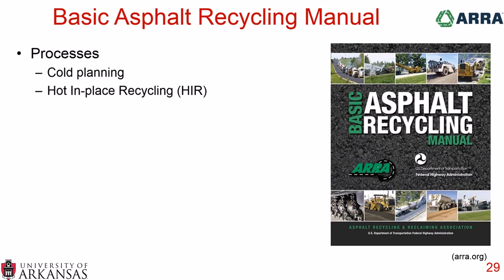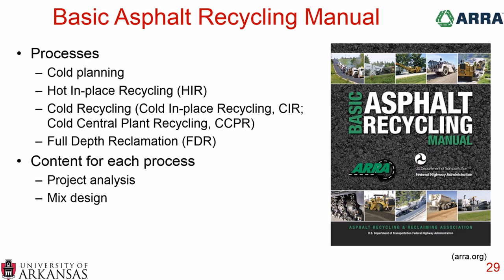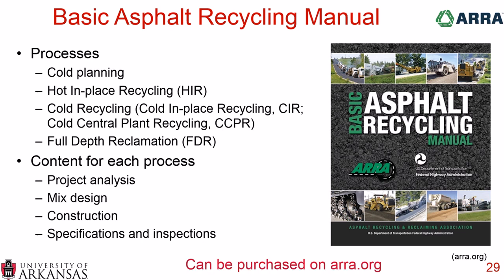The BARM, the Basic Asphalt Recycling Manual, this is a fantastic resource. It talks about cold planing, it talks about hot in-place recycling, it talks about cold recycling, which is both cold in-place recycling, CIR, and CCPR, cold central plant recycling, and it talks about full depth reclamation. So lots of good resources in here. And it goes deep into the project analysis for each of these treatments, the mix design, the construction, and the specification and inspections. And this can be purchased on the website arra.org. Very good resource, highly recommended.